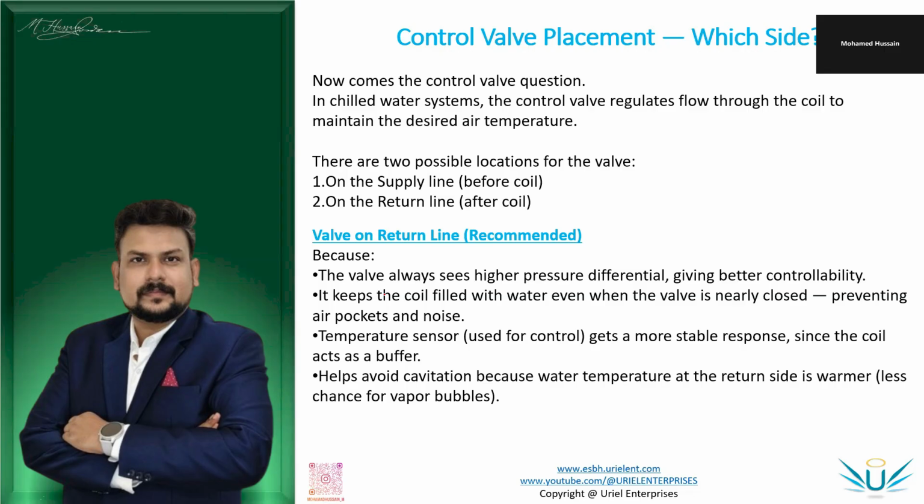Recommended is the return line, because it will fill the cooling coil with water completely, and because a little bit of pressure is always required for better controllability. If you place the valve before the coil on the supply line, the pressure build-up will take some time, and during that time the temperature will increase. Even a few minutes will impact a lot of energy.